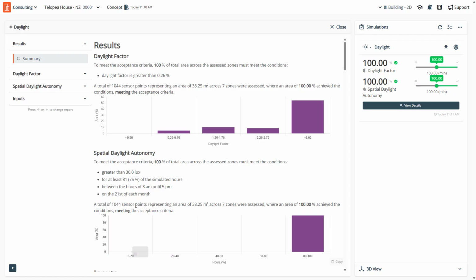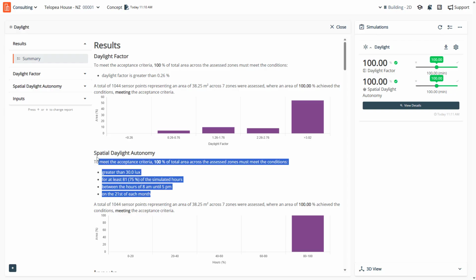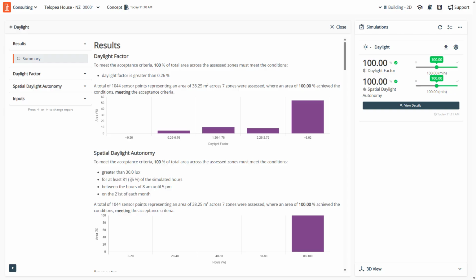That's generally a better way to do it because I think the rule set is clearer and there's a direct relevance to the stated method within G7, rather than just hitting the numbers over here that are determined on a climate basis perspective. So I have a preference for this, and daylight factor is not particularly useful in terms of a daylight metric, but that's another conversation altogether.